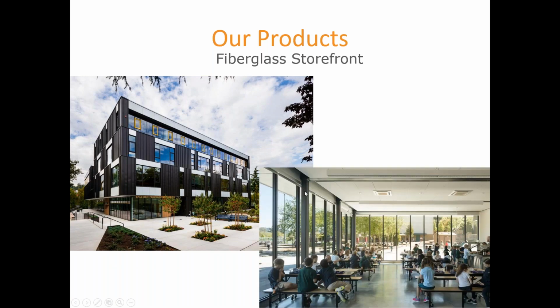Fiberglass storefront windows, and the interesting part here is, yes, you can use them for storefront. They're way more thermally efficient than what you'd normally use. They perform like curtain wall in terms of air tightness and water penetration resistance, but they're far less costly than curtain wall, and they're factory finished. So they come as factory built units that just need to get fastened and sealed to the building, and then the installation's done, as opposed to being stick built on site.